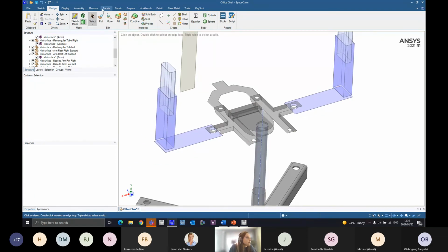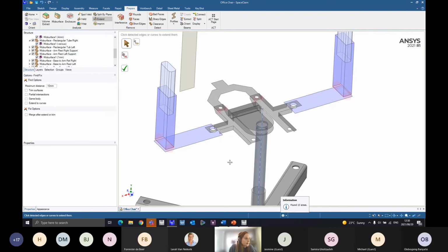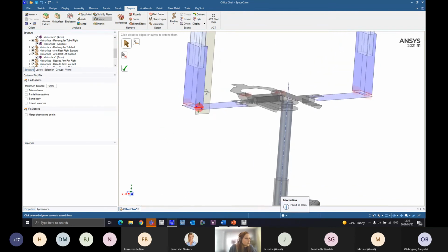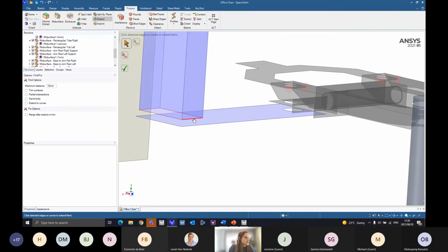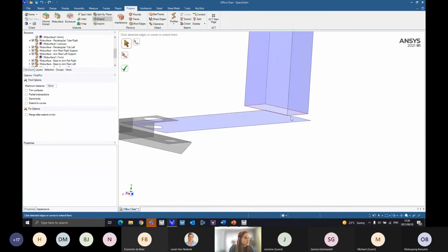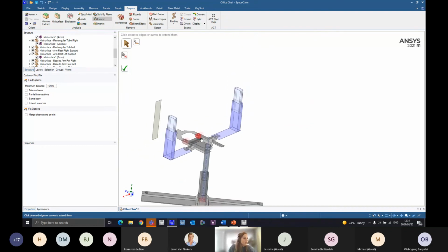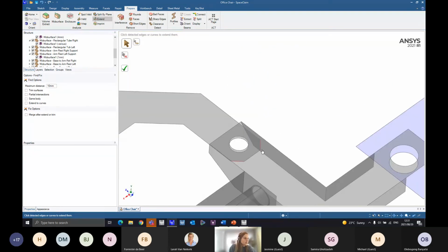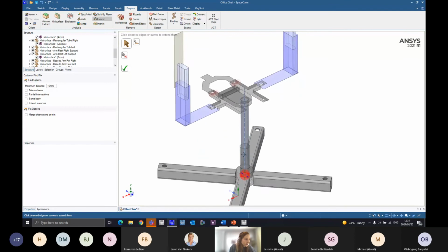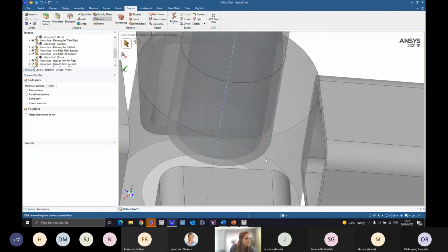So you can do this by, I usually use the extend tool. So then it just highlights the areas that I can extend to an adjacent mid surface. Those are the ones I'd like to extend, and maybe some of those as well. These I don't think are necessary. Those are okay. Maybe this one is probably a tiny gap there.